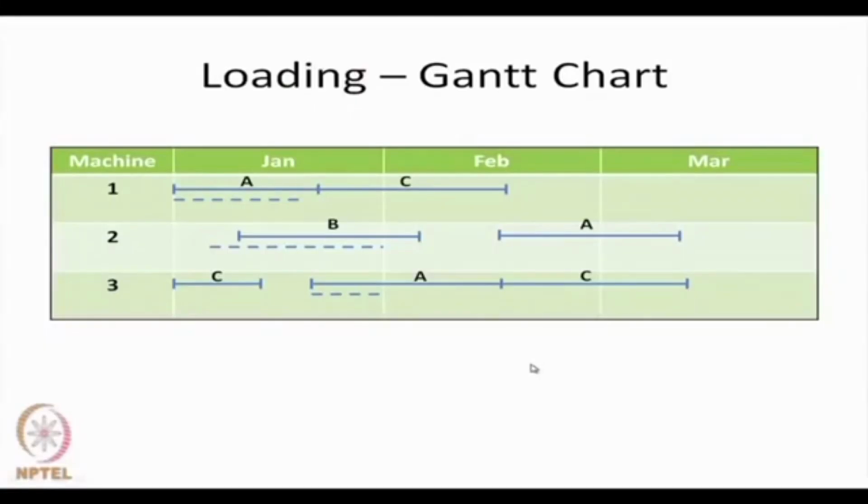That means the dotted lines are put so as to indicate whether the work has started ahead of time, the work is completed on time, or the work is behind schedule. So, these charts are very important and are called Gantt charts for order control, and this is Gantt chart for machine loading.